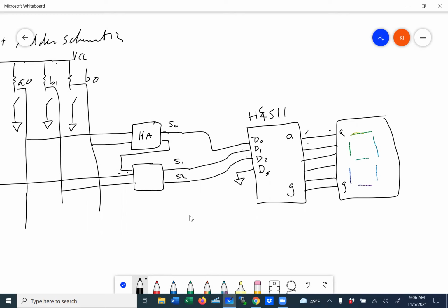And then there are a couple of other pins. You've got to read the data sheet and make sure you set the control pins so that you're operating this one properly, like there's an enable pin and a light pin, and things like that you have to set. And of course, you have to have the VCC connected and ground connected and all that, which I'm not showing. Of course, I'll just go ahead and put this schematic.